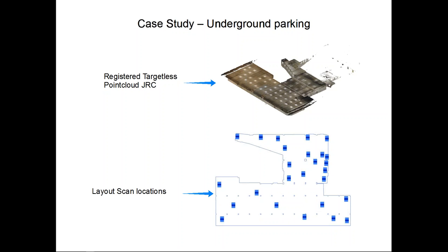Tilt and turn targets, paper targets, flat targets, whatever type of target might exist. We try to get out of that pattern because we observe that targets are cumbersome to carry on site. If you consider that one of our tilt and turn targets weighs 2.5 kilograms, and for this project alone we would need like 20 targets, you can already imagine that with 2 people you reduce a lot of extra weight, a lot of baggage to carry around.